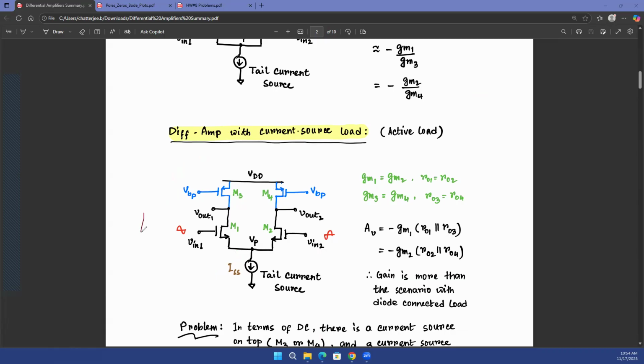So for example, let's say I have a current source, and then I have a PMOS over here. I diode connect one end of this PMOS and then connect the gates of the two PMOSs together. So whatever current I have flowing in this branch would be the same current flowing in this branch, if your M3 transistor and, let's say, this transistor M0 have the same W over L ratios.